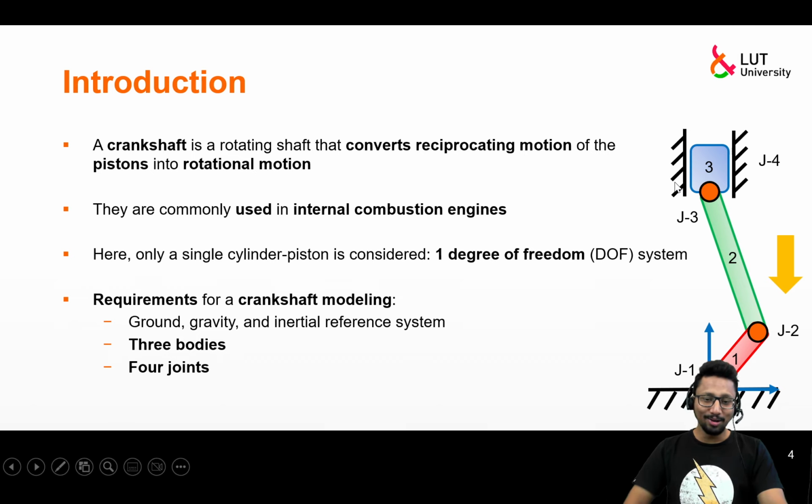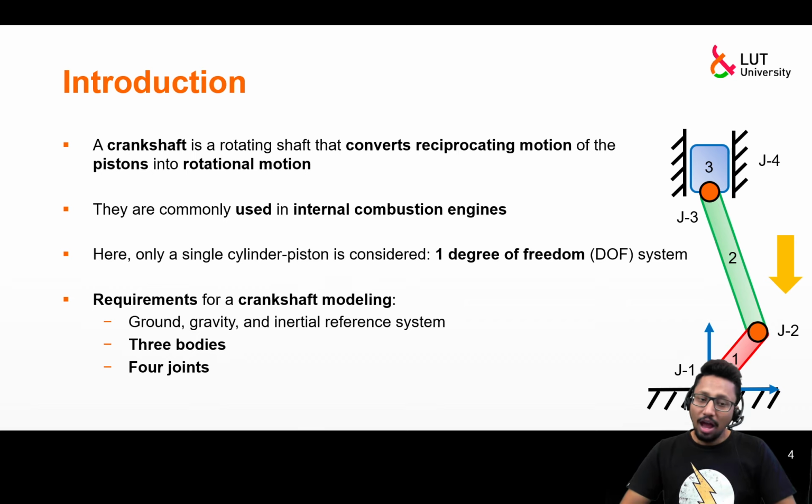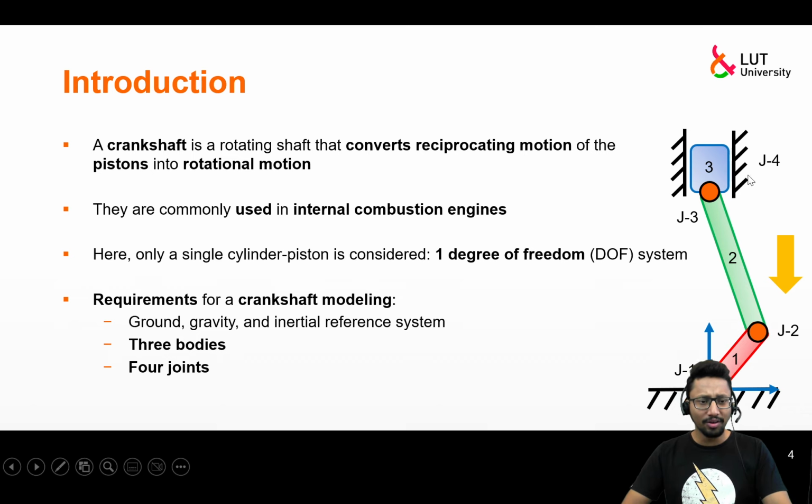I will not say the mathematics is wrong, but we assumed the joints to be revolute joints, right? And there is where we made a mistake. Of course, in the beginning, we are going to model all these joints to be revolute joints, and of course, we know by default this is a translational joint, so we are not going to talk about that. But in 3 dimensions, you realize you are introducing redundant constraints.